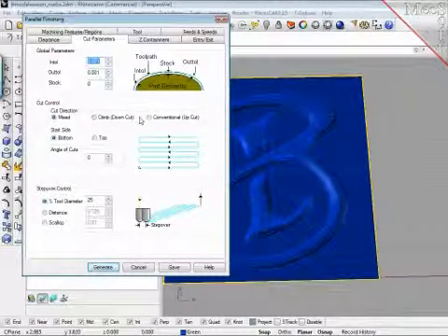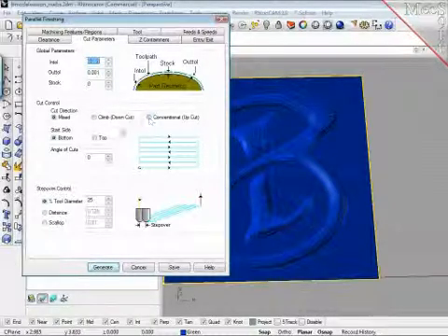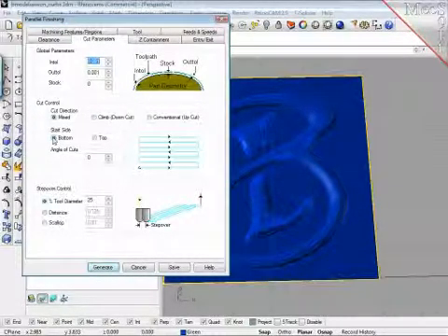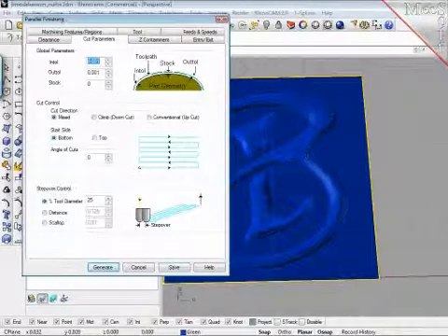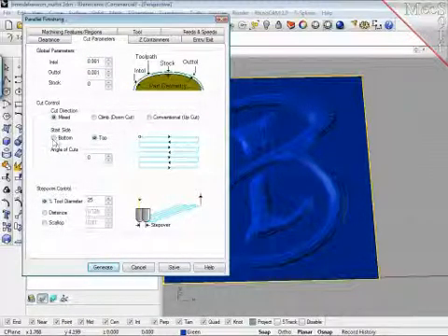If you have very brittle materials like Macassar ebony in woodworking or palm wood, then it is very, very good if you can control this to minimize blowout. And in metalworking, you can determine the tool marks you may leave. Then start side, you can determine which corner of the piece you will start with your tool pass. You can see here the direction of the start point changing.